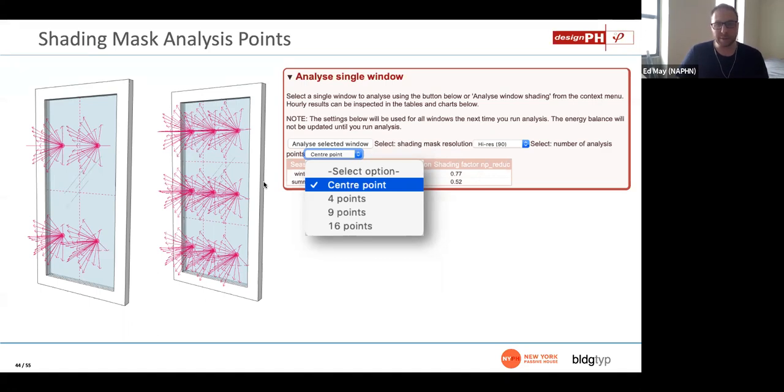So we can significantly increase the number of hours our computer is going to chug away if we go up to 16 points and very, very high resolution. Now that may be warranted and necessary for your project, and you may want to do it. But typically we work using the lower resolution, get everything rigged up, and get it all working properly. Then once we're certain that everything's working, that's when we would shift to the really high resolution, go get lunch, come back after that, and see what we got as output.